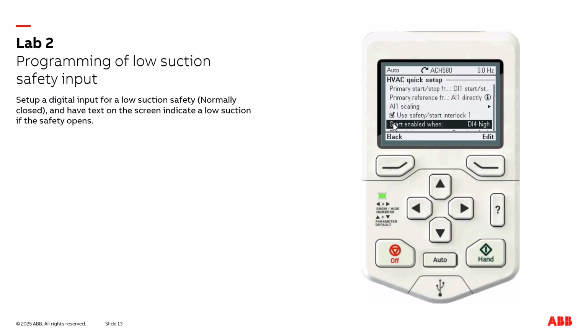And here you can see use of start interlock 1, check, and DI4 high, meaning in order for the drive to run, digital input 4 has to be closed. Okay, so that's already there by default.